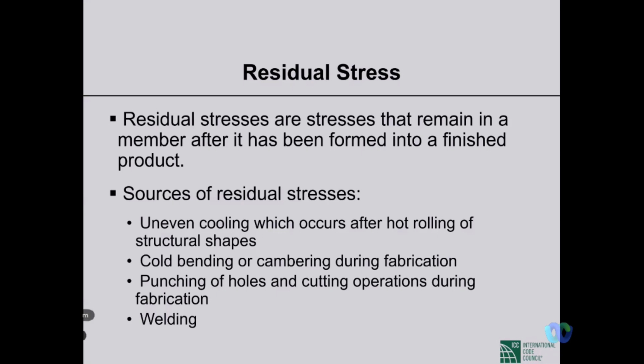When we punch a hole, just by the side of those holes the material is no more elastic, because when you cut out material, just adjacent to the cutting surface, the material becomes inelastic. That means the level of strain is much higher than yield strain, so that causes stress inside the material. And as I said, welding, which is similar to uneven cooling.